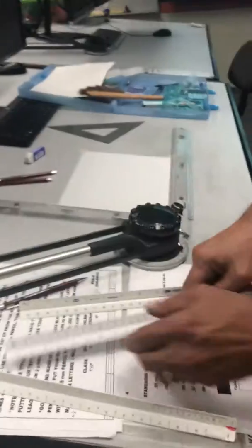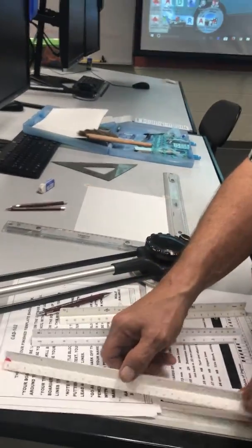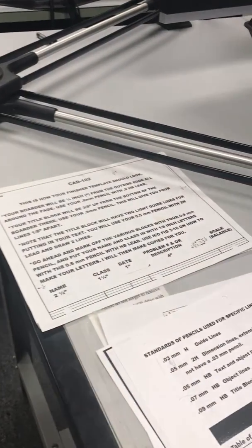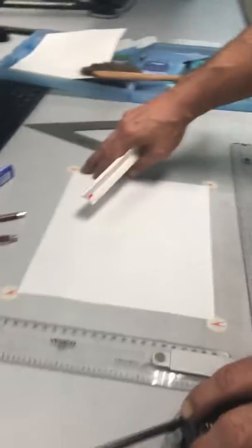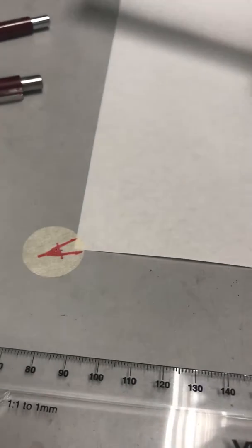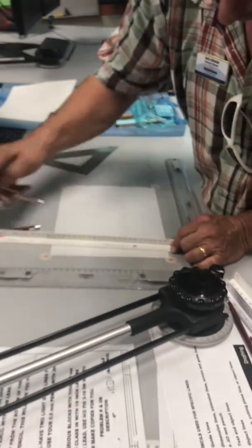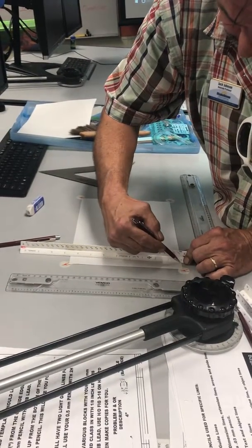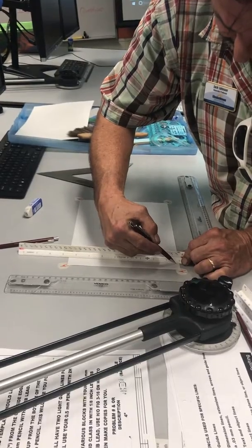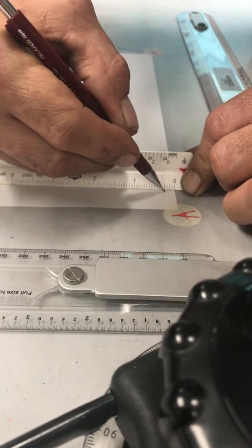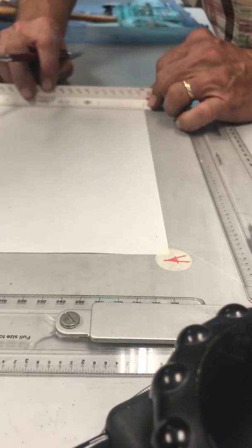Okay, so let's go ahead and look at our title block. Our title block needs to be, looks like we're going to have a 1/4 inch around. That's kind of why I put this tape down like that, so I could have a 1/4 inch. So what I'm going to do, I'm going to take my 16 and I'm going to lay it on the edge, and I'm going to barely mark 4 ticks, which is a 1/4. 1, 2, 3, 4. All right, so there's a 1/4 there. And I'm going to mark a 1/4 here.